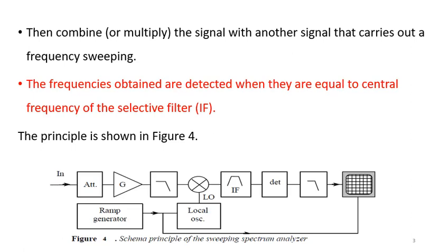And when this local oscillator signal is mixed or multiplied by the high frequency, which is normally radio frequency, we obtain what we call intermediate frequency. And this intermediate frequency is nothing but the intelligence contained in the radio frequency, in such a way that the frequency from the local oscillator has now eliminated the carrier frequency.